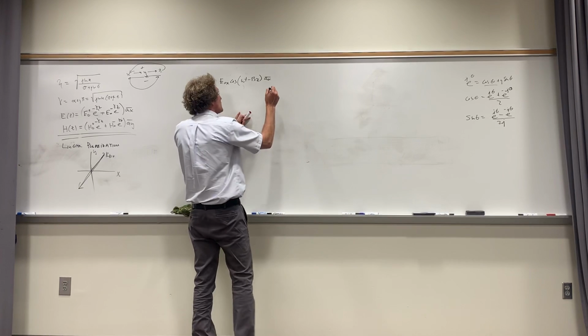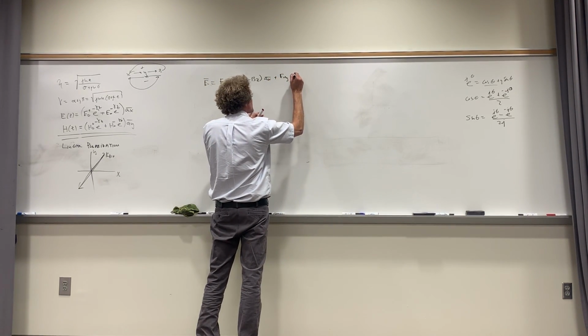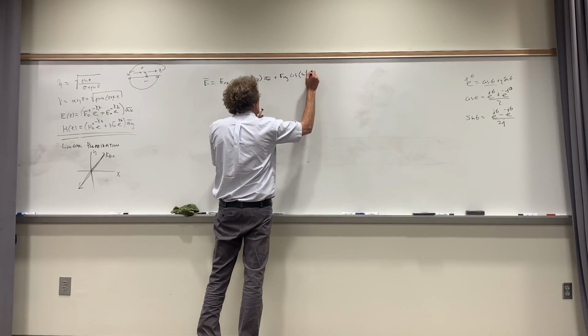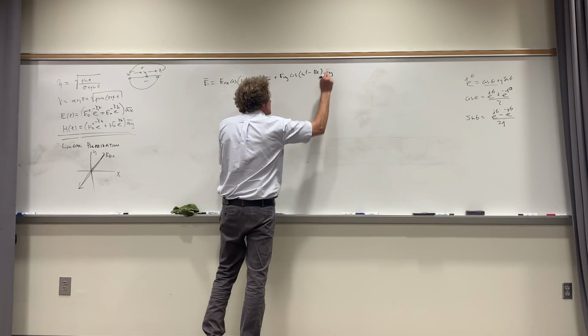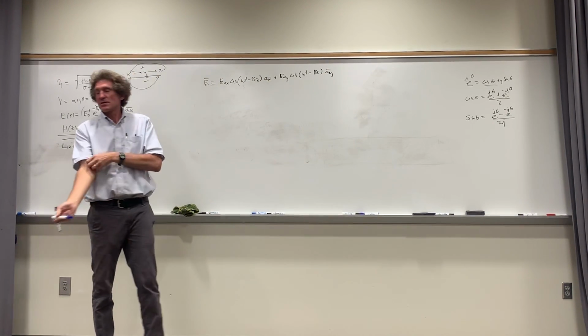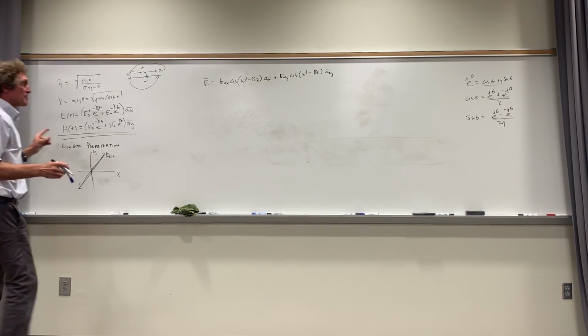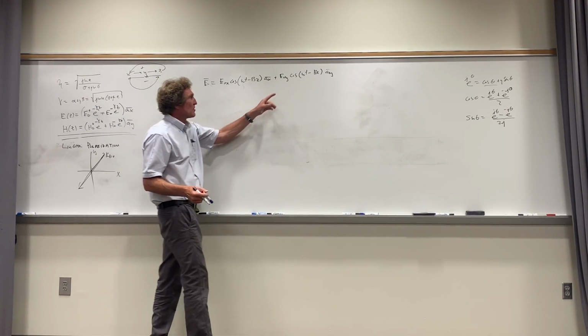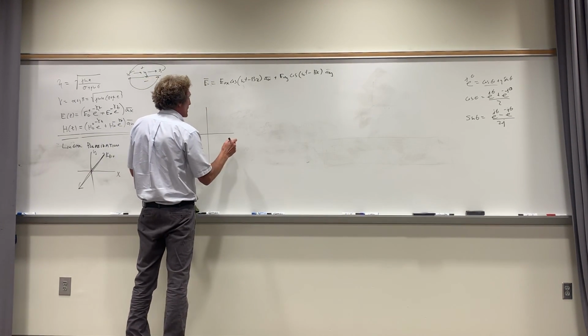This is time domain. Then it would have some plus some E naught Y, and it would have cosine of omega t minus beta z in the AY direction. Now if you take a look at that, just let z be 0 for a second. You see how the cosine omega t in both of those grows at the same rate, right? So at omega t equals 0, it has a maximum value of 1, and EX 0 and EY 0 would be at a point.